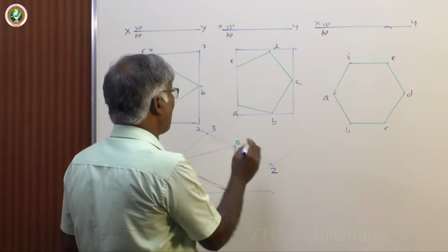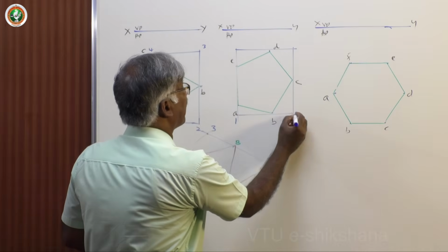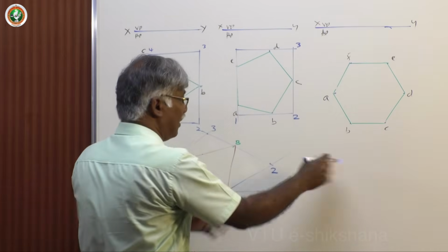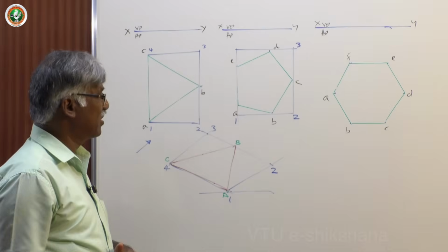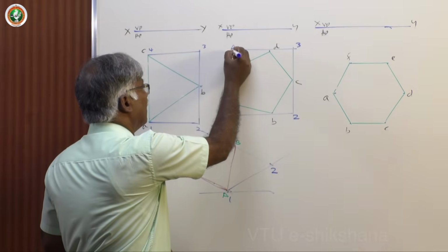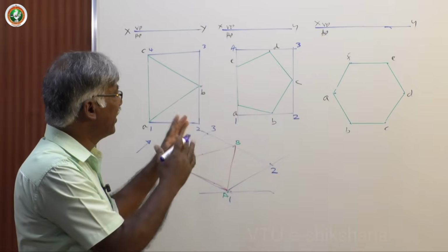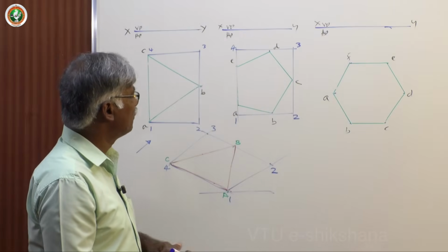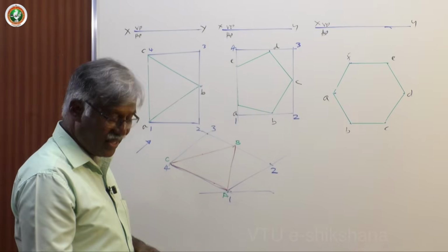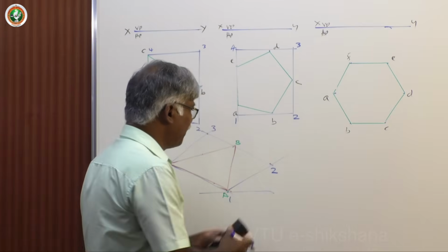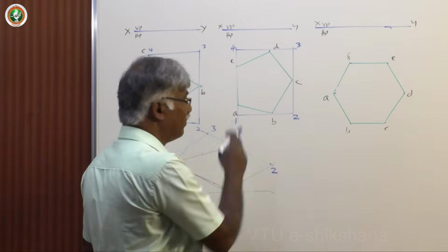Majority of the time people draw a square. Okay. As the isometric projection, take equal distances. Here 1, 2, 3, 4 is the box for the pentagon. You have to cover all the corners A, B, C, D, E. Then start working for this particular problem.